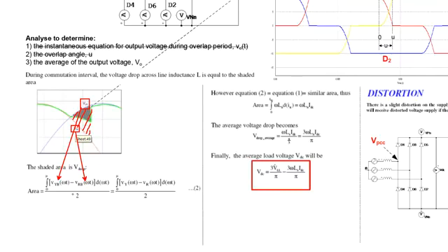Then you divide by 2, because we know that the output voltage is in the middle between the two line to line voltages. So to get this first area, we just divide the whole area by 2. This is what this equation does, from 0 to u. Again, Vy minus Vr, you can cancel the Vb, so it is just left with Vy minus Vr over 2.